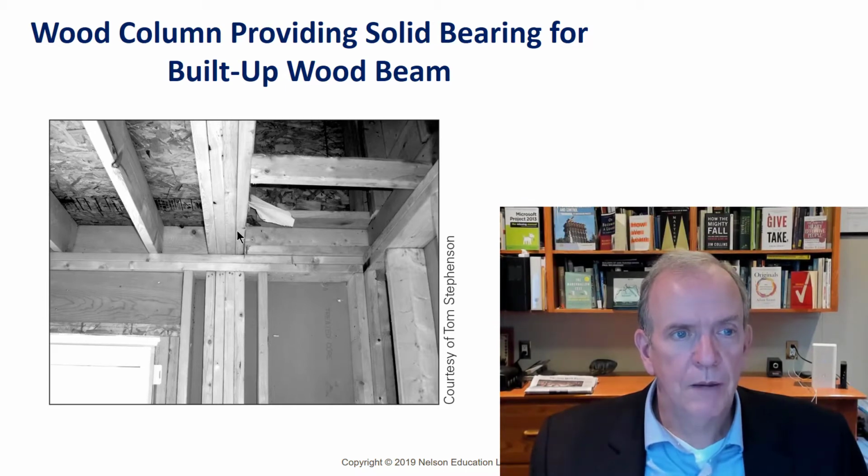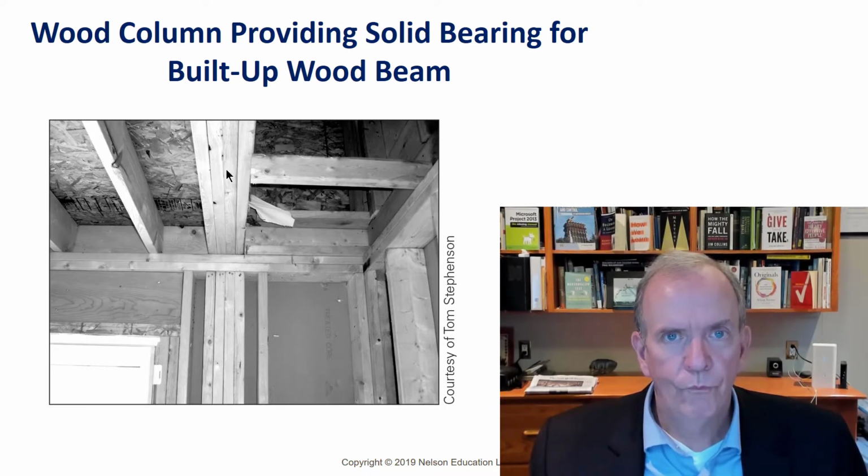So when we do built-up wood beams and the transference, we talked about built-up wood beams. Remember, this would be called how many? 4-ply. So that would be a 4-ply beam. Well, we're never going to have fewer plies of the solid bearing underneath it. So we shouldn't have two studs carrying a 4-ply beam. So it's going to be at least that much. In some cases, you may have to put more than what the beam is, depending what it's carrying.